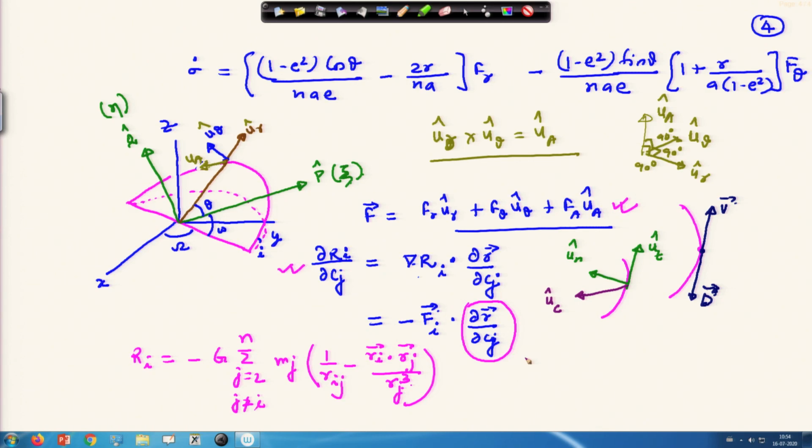So, here in this case the drag will be modeled properly if we represent this in terms of the tangent unit vector, and the normal to this is called the principal normal, and what is appearing here as the u c is called the binormal. So, along the tangent direction, along the principal normal direction, and in the binormal direction we require all the forces. So, this model also we will look into shortly once we finish this part.